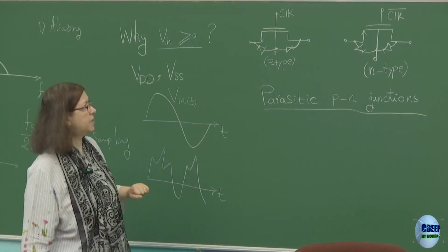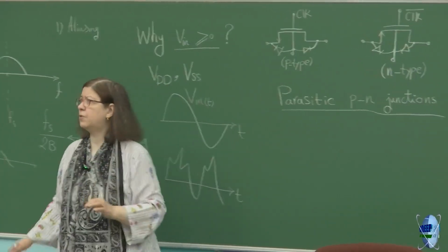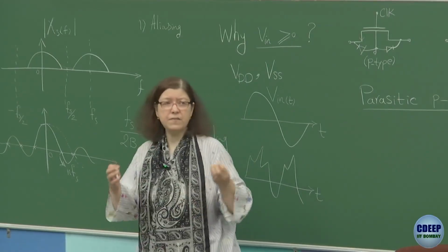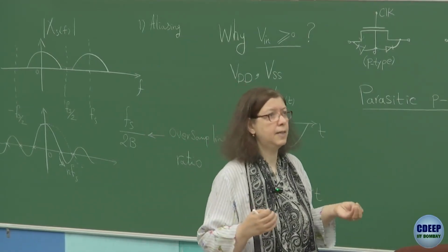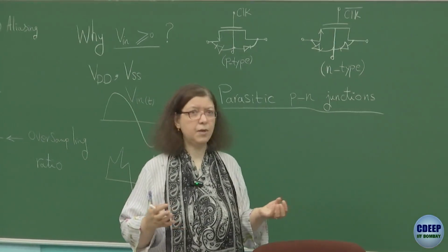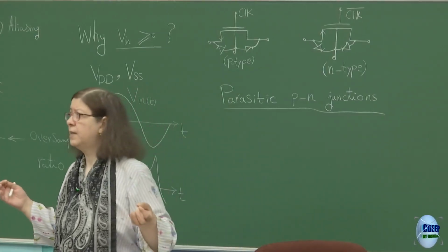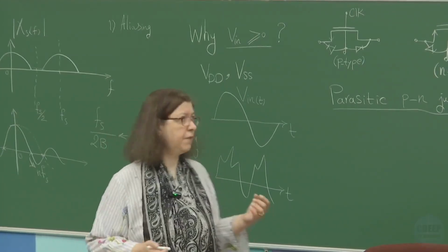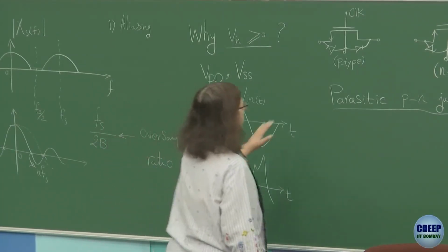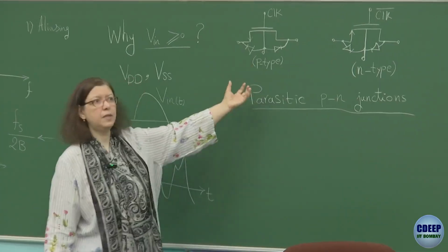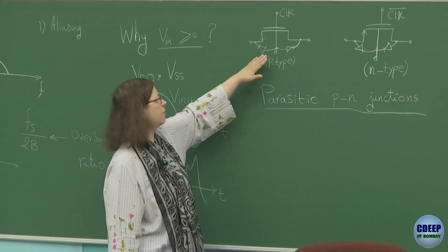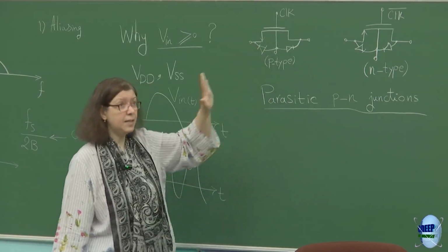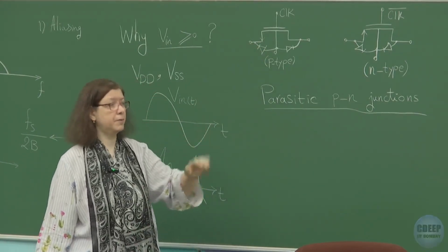To keep them reverse biased, for each and every diode, you need to take care. This is not easy when you have an analog circuit with, say, 500 transistors, or a mixed signal circuit with, say, 100,000 transistors. That's not practical. So what they say is that you bias the bulk as one of the conditions. You can, of course, bias it by shorting it to source or drain, but these are conditions that we have to be careful about.